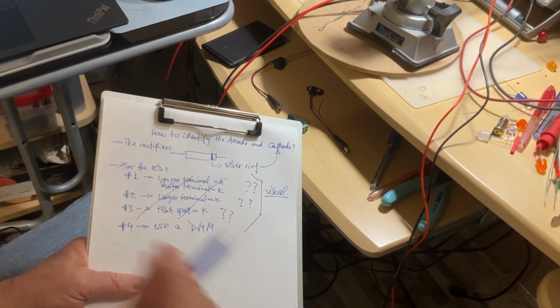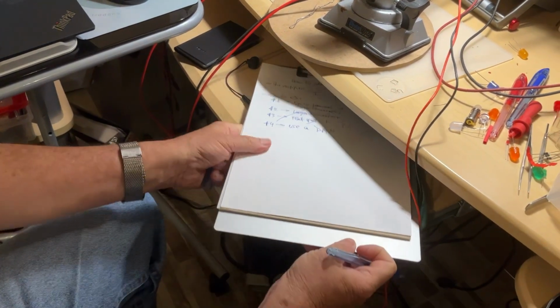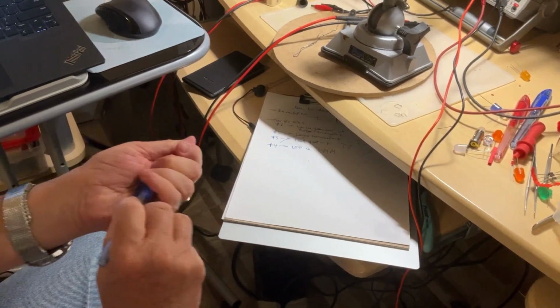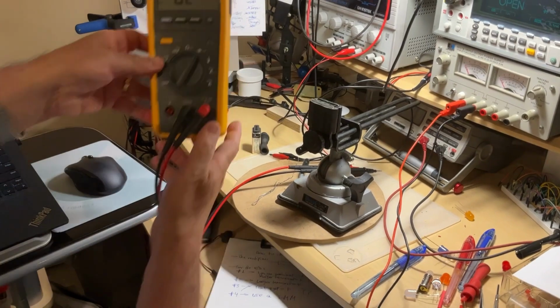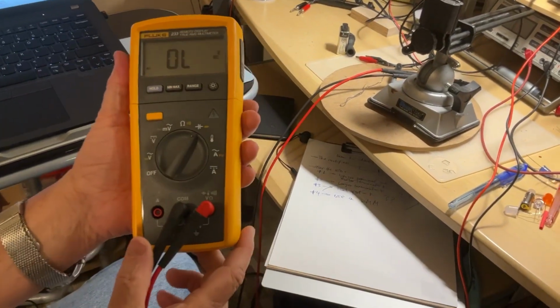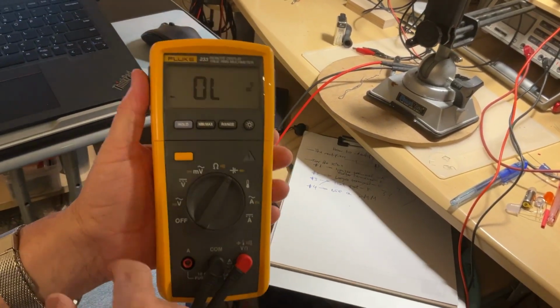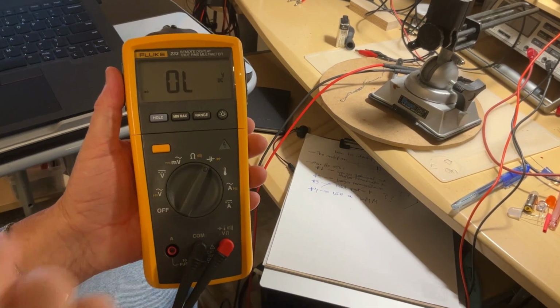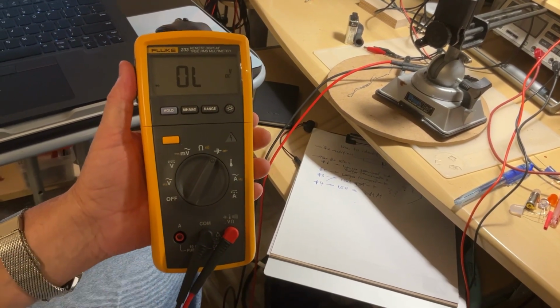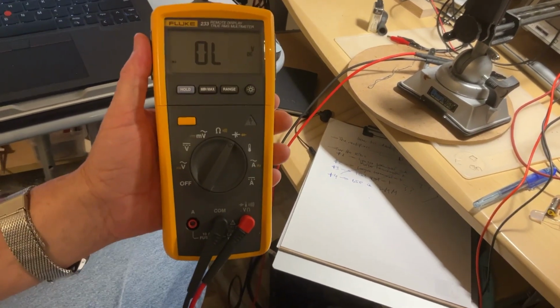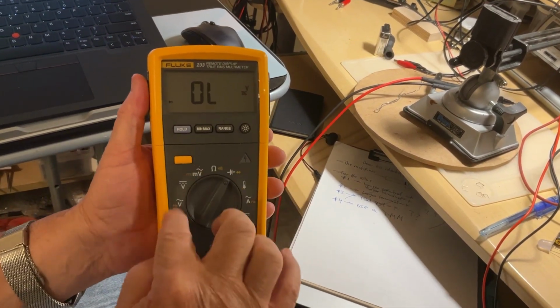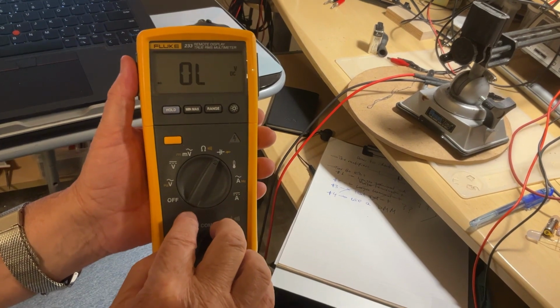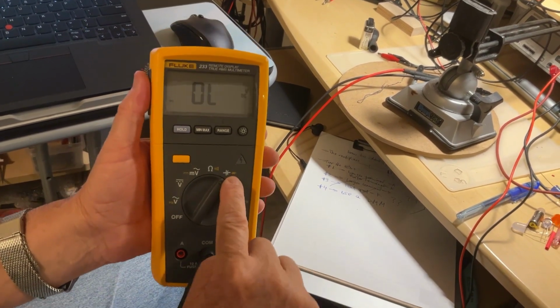Now, we're gonna have a problem as well. I'm gonna use a multimeter. This one here, it's a good quality multimeter. And all the multimeters regardless the quality, regardless the price, they have a position somewhere around the rotary switch, like this one here with the symbol of a diode.